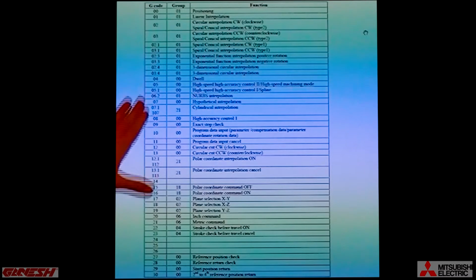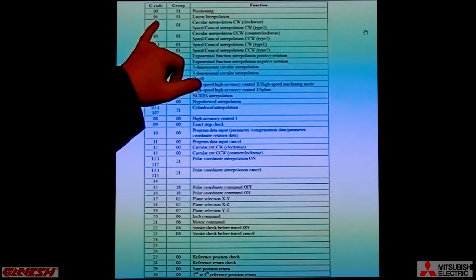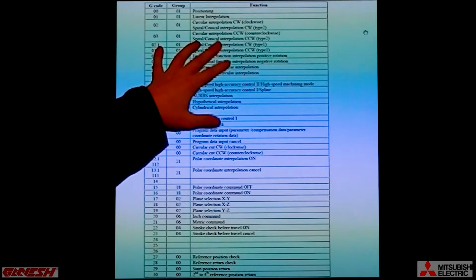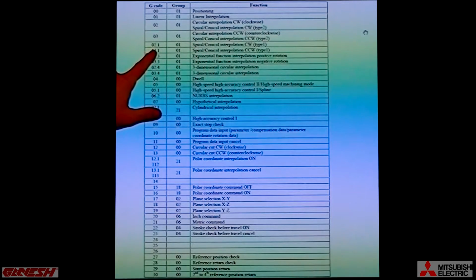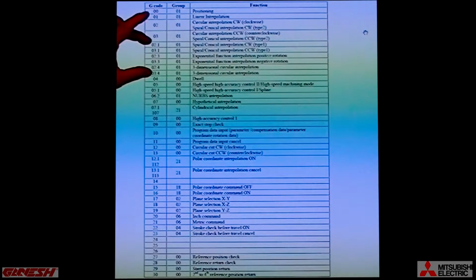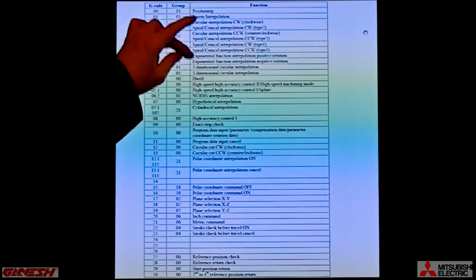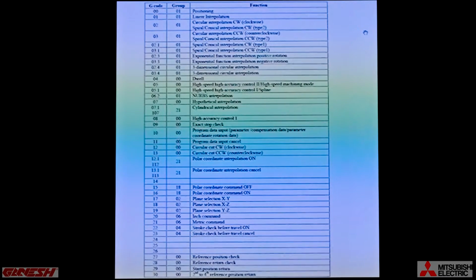So here's the list of different G-codes. So G00, 1, 2, and 3, we know and we beat to death over the last several hours of practice that we've been doing here. G02.1 and G03.1 are commands that are only available on our advanced control, but what they involve the use of is spiral interpolation.